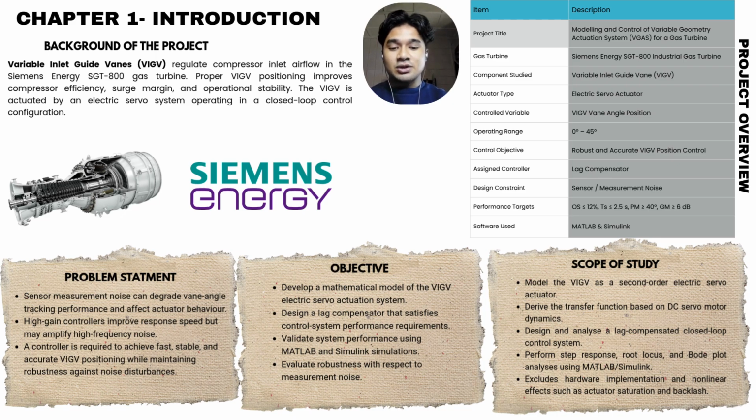The vane position is controlled using an electric servo actuator operating in a closed-loop feedback system. The main challenge in the control system is to reject all the measurement noise from the angle sensor. Excessive noise can affect the vane angle tracking accuracy and cause unnecessary actuator movement. Although a higher controller gain can improve the response speed, it may also amplify high-frequency noise and reduce robustness. Therefore, a control strategy is required to achieve accurate tracking while maintaining stability and noise rejection.